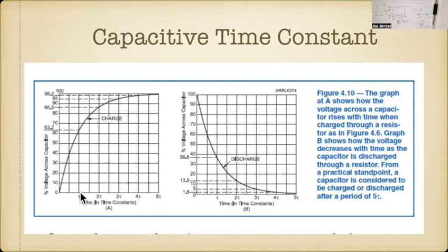In our example of 50,000 ohms, T is 5 seconds. So this would be 5 seconds, 10 seconds, 15, 20, and then 25 seconds, which at that point they would consider it to be at full voltage, which for us with our equipment is going to be 5 volts.